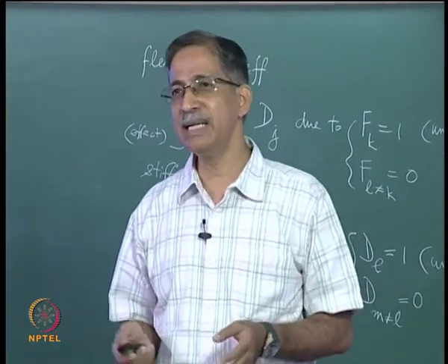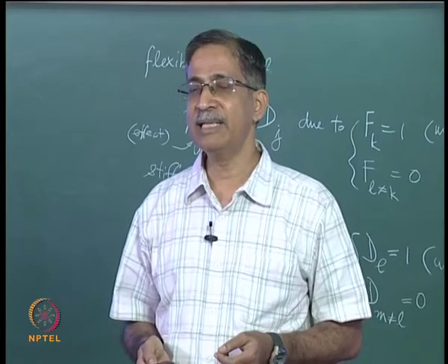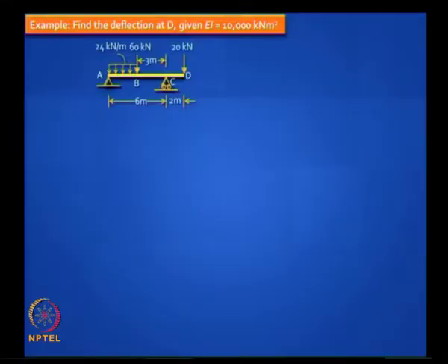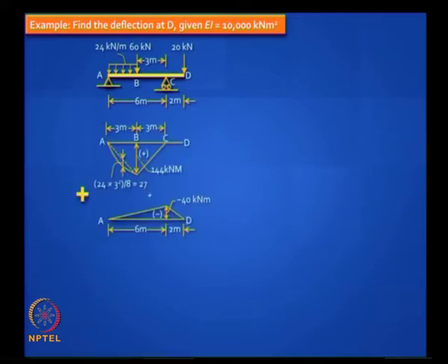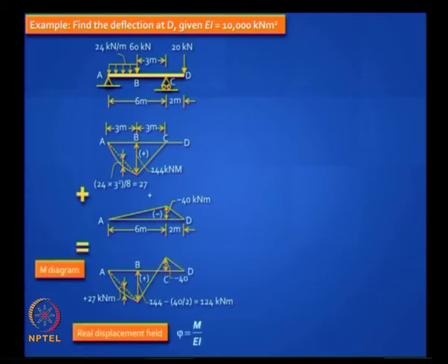So let's take just one example and see how it can be applied. This is a little difficult. It's a simply supported beam with an overhang subjected to some arbitrary loading, and the question is, can you find the deflection at the free end? Well, you have to draw the bending moment diagram, and it's good to separate out the curved part from the straight part. There are some shortcuts involved. I suggest you go through it carefully. We've done this last year.